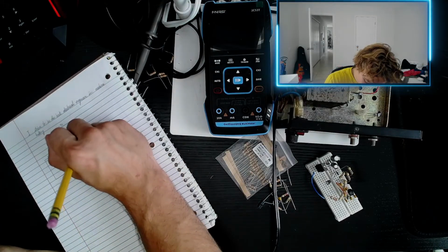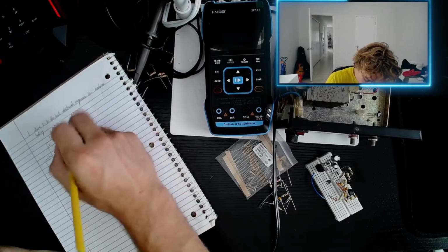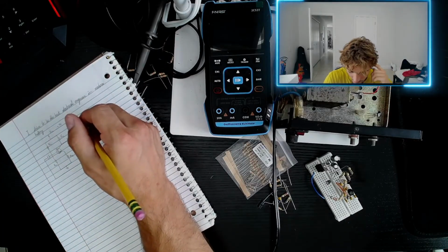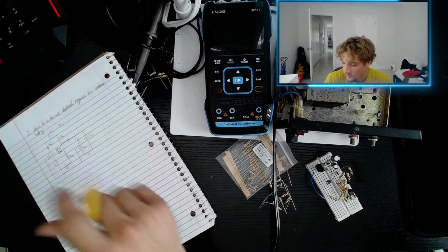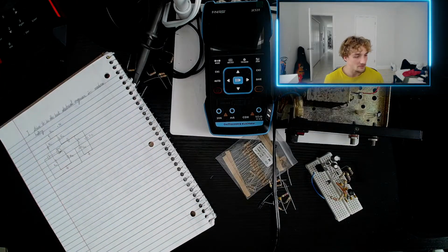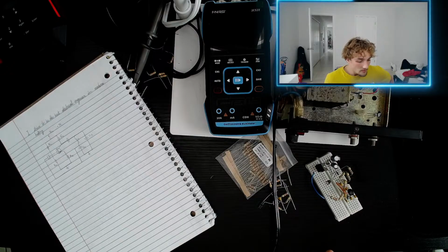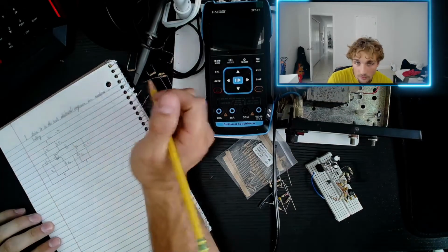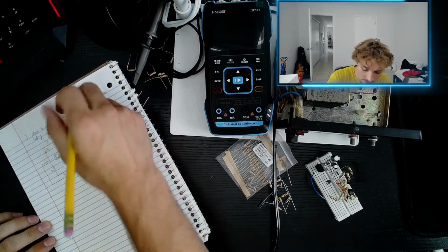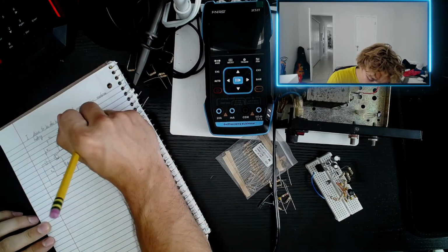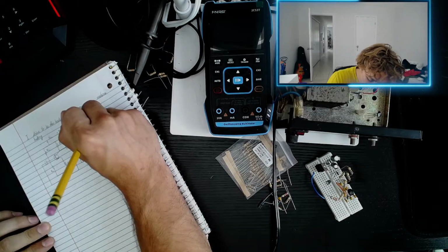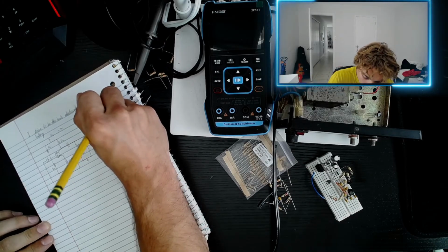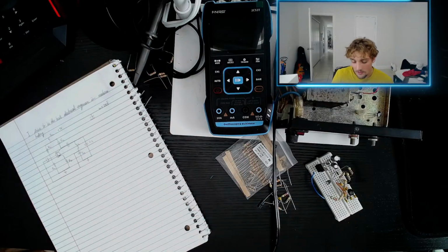Okay, let's label this L. We'll consider him C2, C1. And then we're not going to label our decoupling capacitors. Those are fine. They're not much to consider. We just want them to be a high capacitance, right? Because the formula for impedance of a capacitor is 1 over omega C, where omega equals 2 pi f, 2 pi times the frequency.